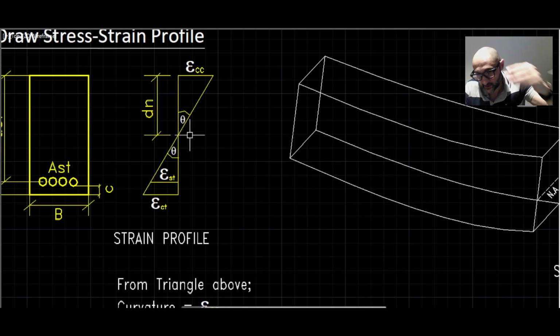Okay, so if the beam was hogging, let's say the beam was giving you a sad face, then the depth would be taken from the bottom of the beam, because that will be compression, to the neutral strain.